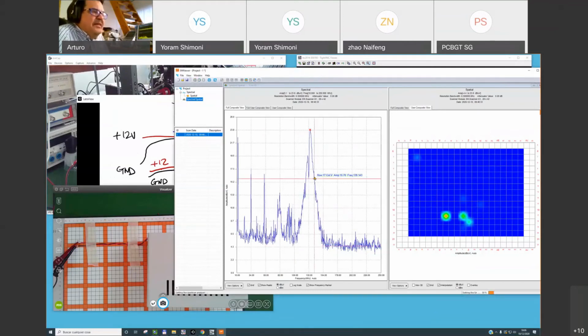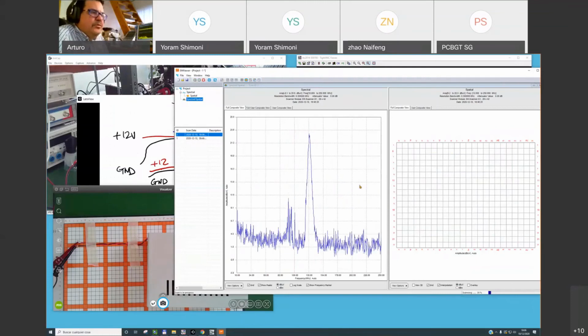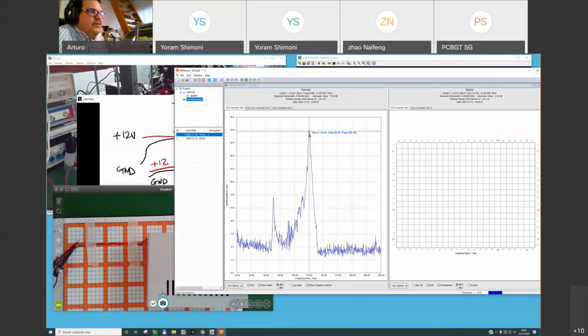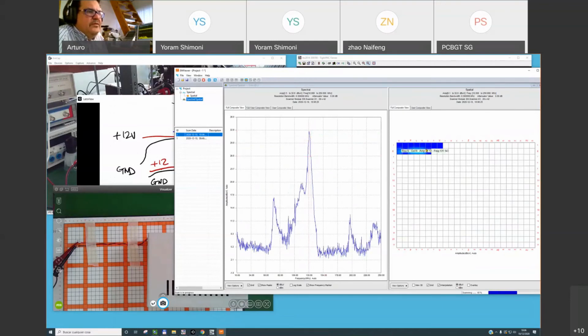Now, again, I will be testing the full number of cells I have selected in the full frequency range from 10 megahertz up to 250 megahertz. Okay, you can see that the system is finding energy at 130 megahertz. So really, we have activity at this frequency in the cable. There are no filters. We will see where the origin of this signal is later. You can see that in the area of row number 5 it is blue color.